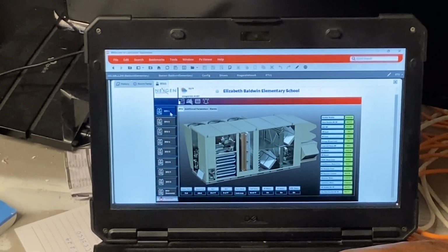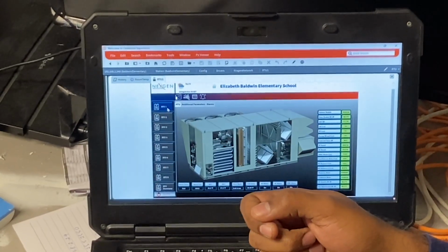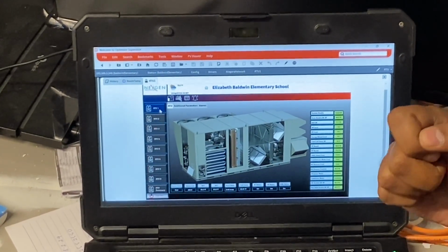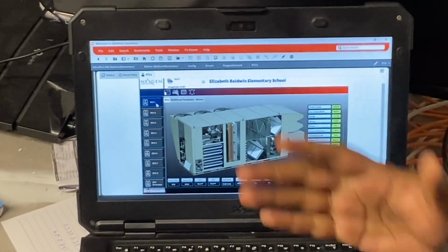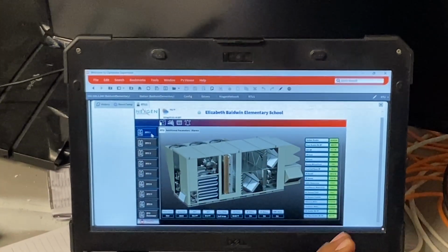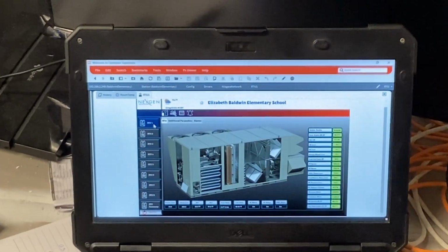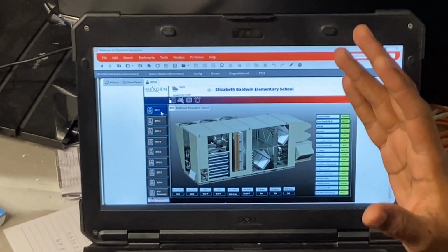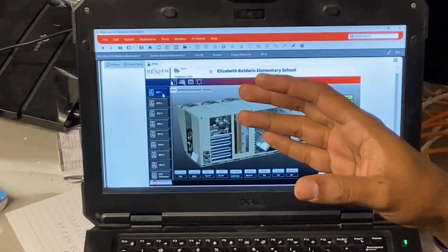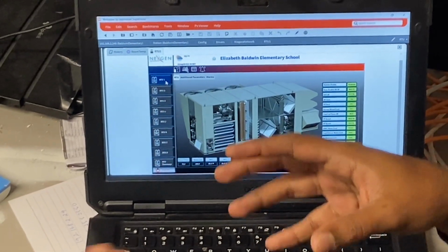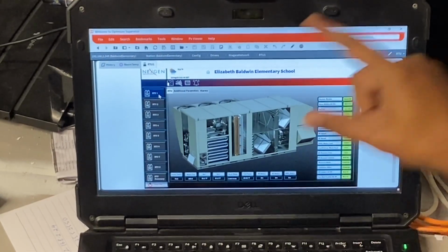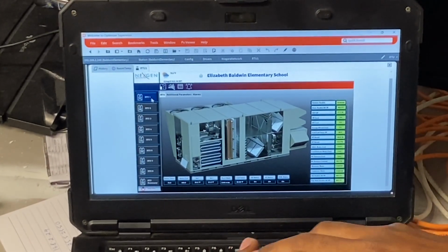Same thing applies to cool down as well. Let's say your temperature is more than 76 degrees, which is adjustable. It is all space averaged; all the VAV temperatures are averaged, so you have a space average temperature. If it could not maintain 76 in the space, that being the set point you keep for the cool down, it's going to do the cool down during the occupied time as well, not only in the unoccupied time.